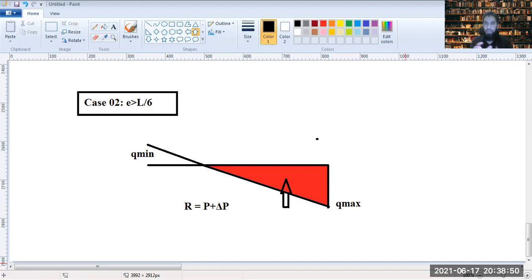Now why is this important? This is important because the system has to remain stable. Now, when does the system remain stable? What is the natural tendency? On the left side, because soil has zero tensile capacity, the tendency would have been to uplift, but it cannot even uplift itself on that side, because the soil is offering no reaction from the top.